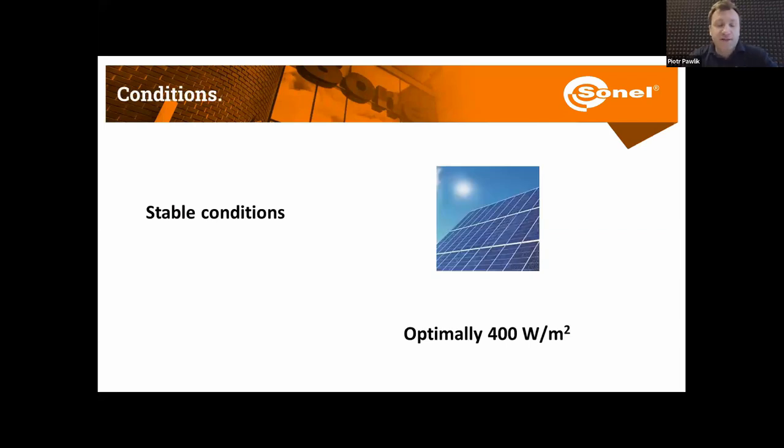Okay, once the visual inspection gives us positive results, we can move on to electrical testing. On the other hand, if we have negative results of the visual inspection, then we stop at this point and write the report, and in the conclusions we give recommendations on what needs to be fixed. Then after it is fixed, we perform the whole verification again. So again, visual inspection. If it's positive, we can move on to testing and then to the report.